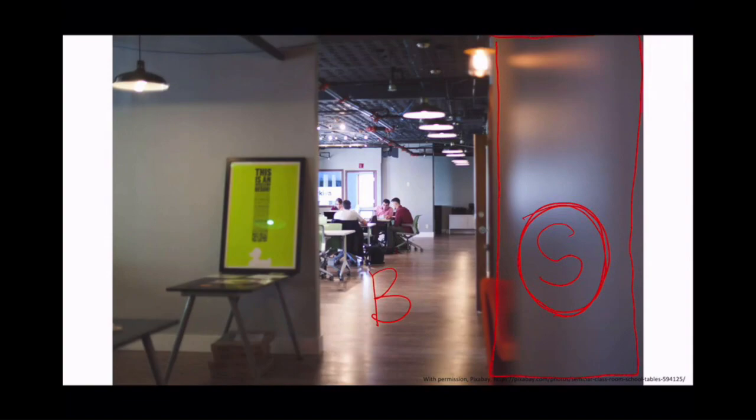And if your occupancy type doesn't happen to be on the list, you have to choose, often in consultation with the code official, an occupancy type that is closest to what the established other examples of rooms is.